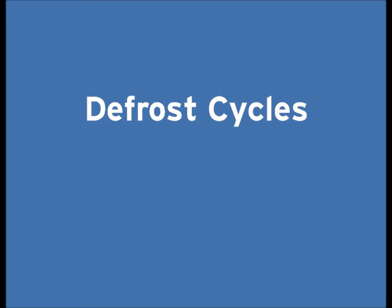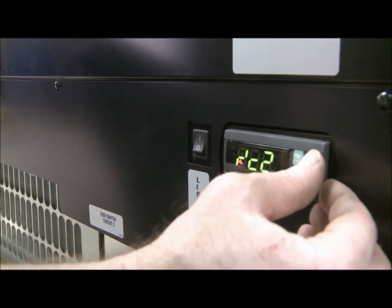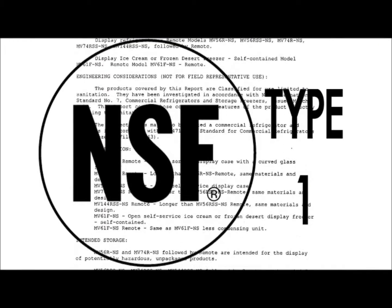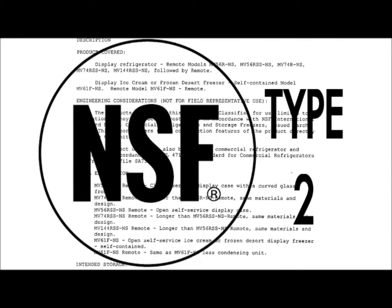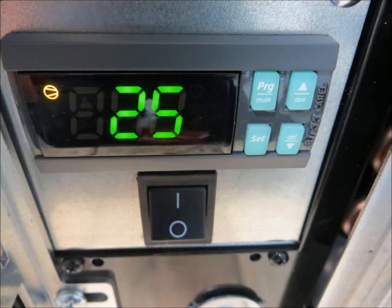Defrost cycles. Our refrigeration controller is preset at the factory based on the ambient conditions the case is designed for: NSF Type 1, which is operating conditions of 75 degrees Fahrenheit and 55% humidity, or NSF Type 2, which is operating conditions of 80 degrees Fahrenheit and 60% humidity. There is no need to make adjustments to these settings when starting up the unit.